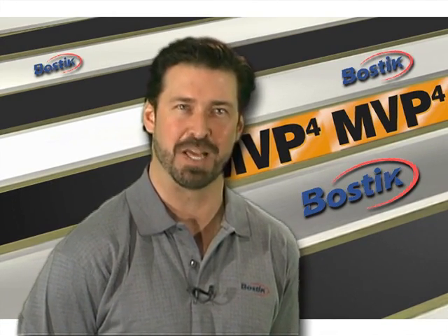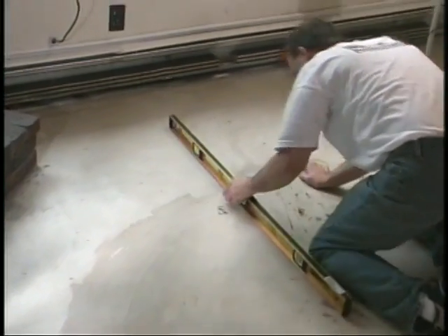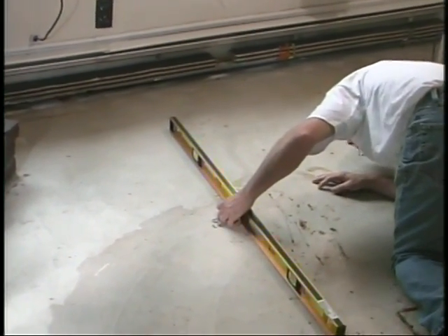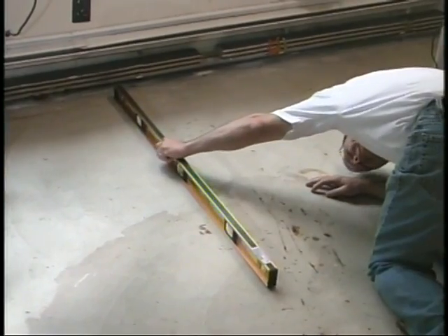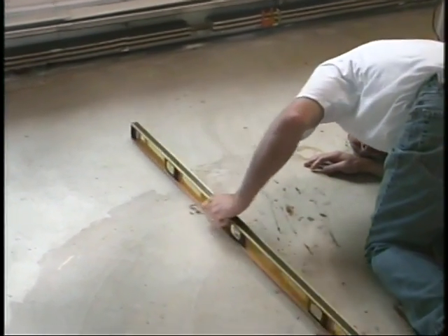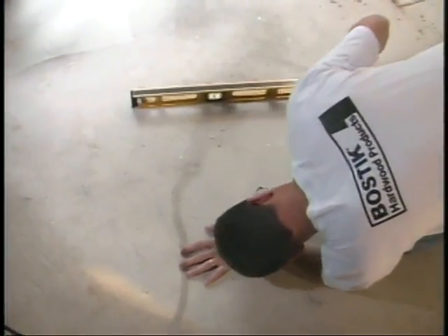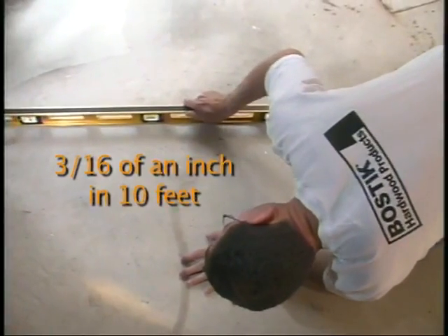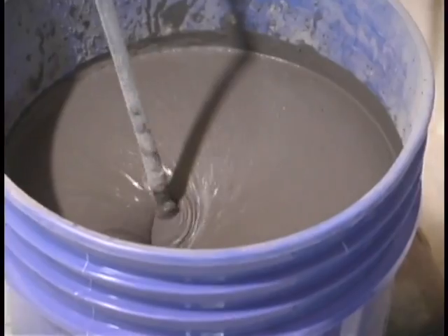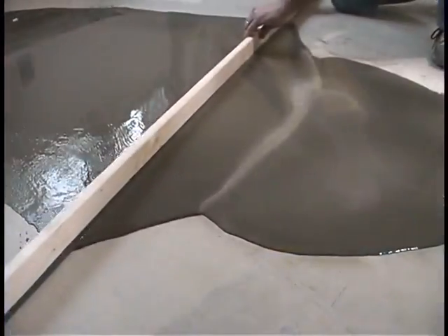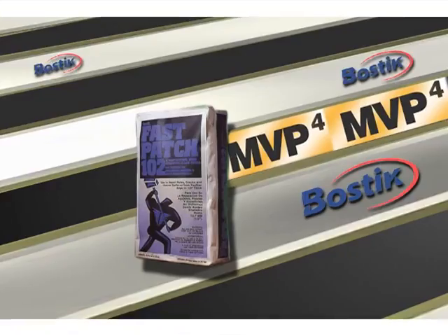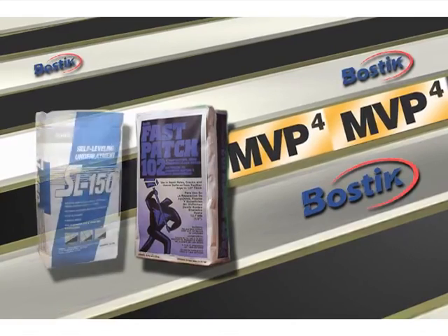Check your subfloor to ensure that it meets the necessary recommendations for a flat surface. The maximum acceptable floor variation for MVP4 is 3/16 of an inch in 10 feet. To achieve this, flatten the surface by using a Bostik underlayment product such as Fastpatch 102 or SL150 to bring the floor into compliance before the installation of MVP4.